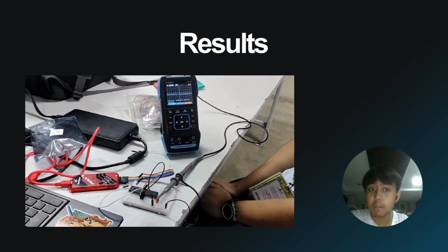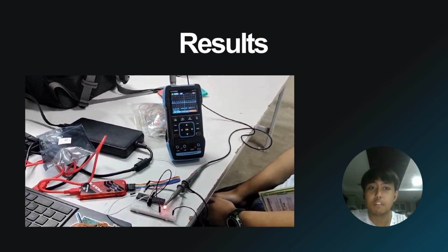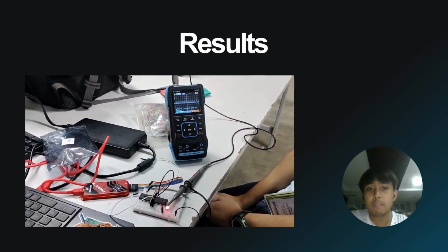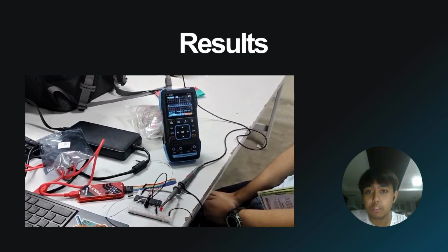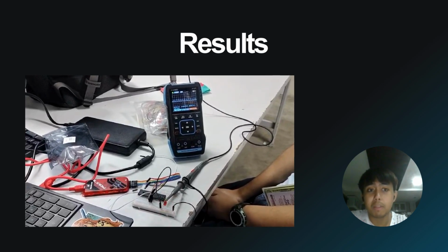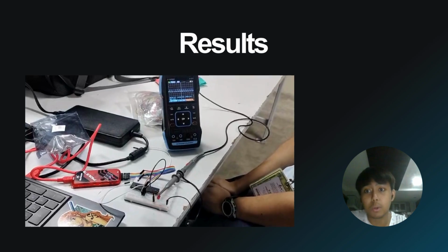For our first experimental setup, it involved an LED connected to pin RA7 of a microcontroller, which is powered via VDD and VSS connections. We had the intention of creating a delay worth 250 milliseconds, and it relied on the delay polling and interrupts that were coded earlier.